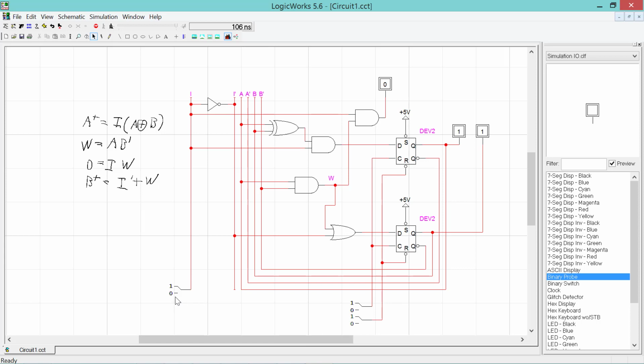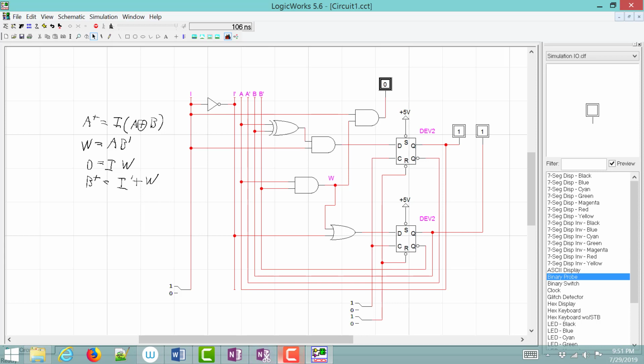Now, this is very odd because we went to state 3, but there is an output of 0. Well, we recognize 3 bits though. Why are we getting an output of 0? The key to remember is that we are looking only on the 0, 1 transition for the valid output value. Remember, on the previous clock cycle, we had an output of 1 here. So when we clock on state 3, it is going to be an output of 0 regardless.